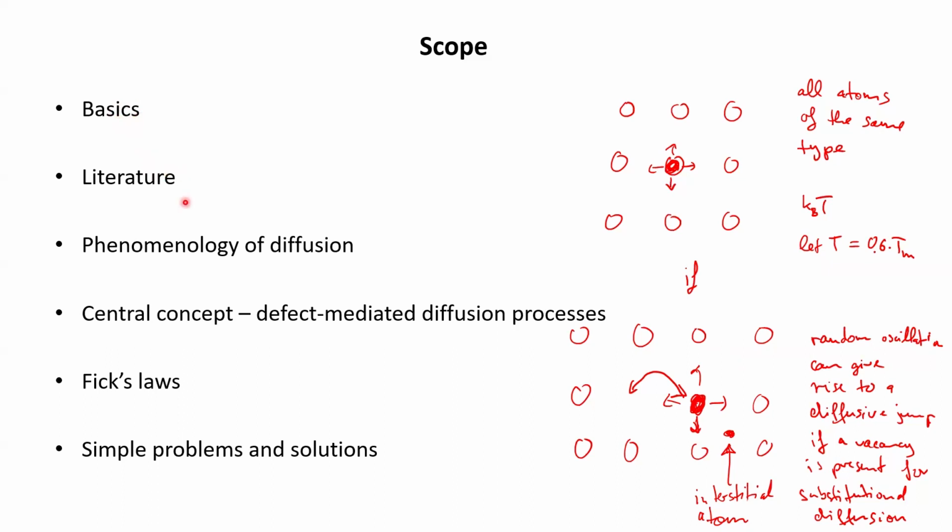Okay. To basics, then give you a list of the literature on specifics of diffusion, because you can also ask yourself, in a normal conventional material, like a piece of steel, where is diffusion going? I mean, you could, let's say, apply a process gas, CO, or any type of carbon-containing gas, and you want the constituents, let's say carbon, to diffuse into the steel to carburize it.